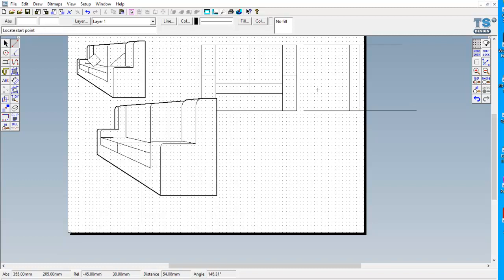I can even do a plan view down there as well. So if I wanted to, I can do my plan view. So plan view and orthographic, just follow it at 45 degrees. Project these lines going down, any line going down, that line's going down, then any line going across. So you can see where we've got down here. So if I project that line going across, just carry that 45 degrees. What I'll do then is place this one under this one, so I can see where it's going to start from. It's going to start from there. This line's going down, so that's going to be the edge of it.